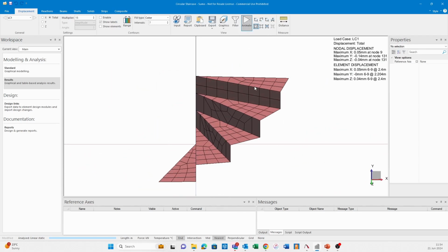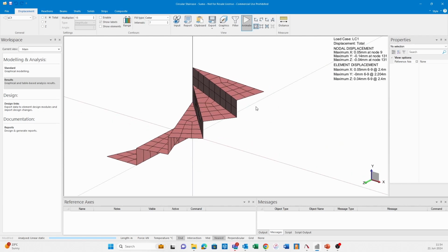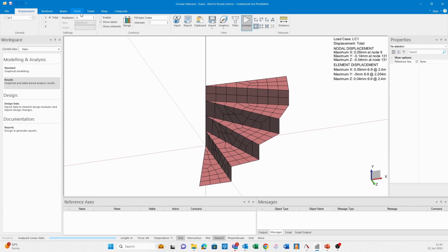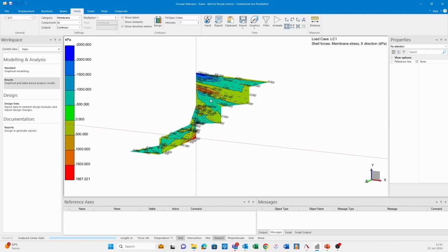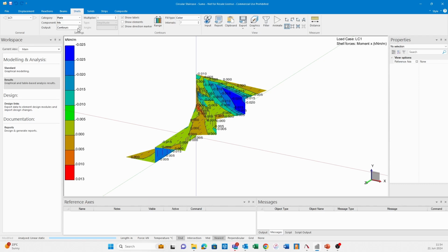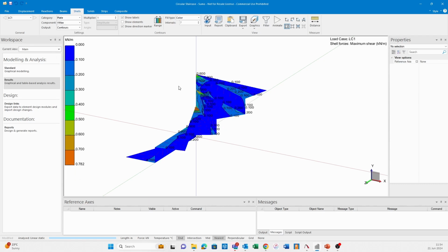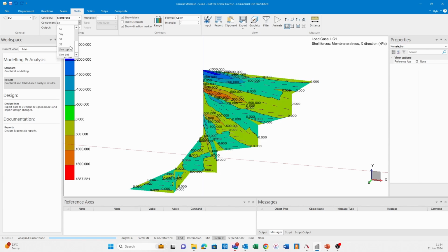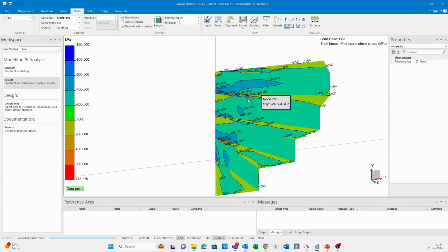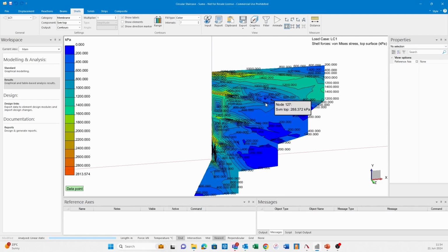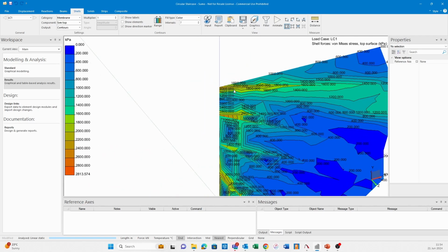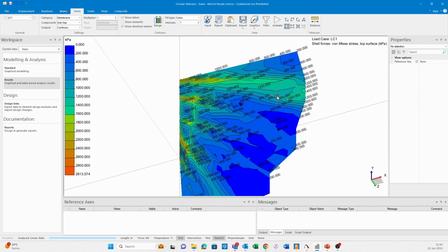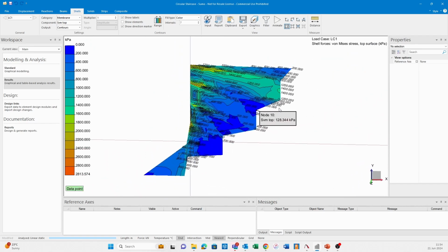All right, but you can imagine if this is all welded plate, especially if it's 10 mil welded plate, that it actually would be very stiff. So now what you can do, we can go to our shells, and here we can look at our membrane stresses, our plate stresses. Okay, membrane shear stress. There's our von Mises stresses. So actually here the stress would dictate the design then.